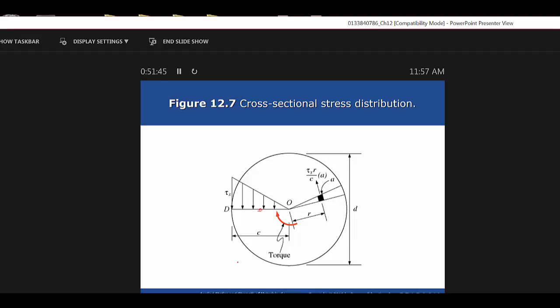Now the torque equation, if you look on page 251. If you're wanting to find torque, the shear stress is equal to the torque times the radial distance, divided by J. Well, what's J? That's the polar moment of inertia, and you will be able to find that on the back cover of your book. And C is the radial distance from the centroidal longitudinal axis to the outer surface, or to wherever you're trying to find that value.